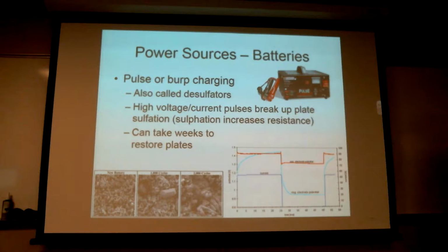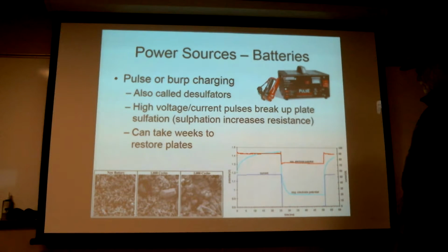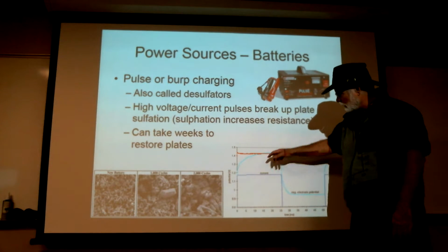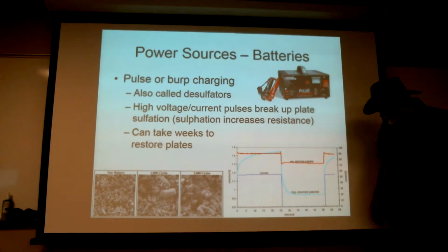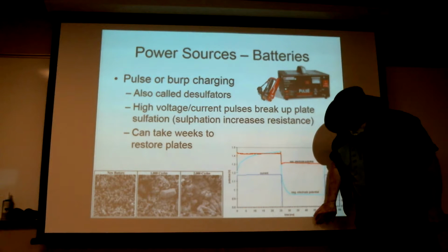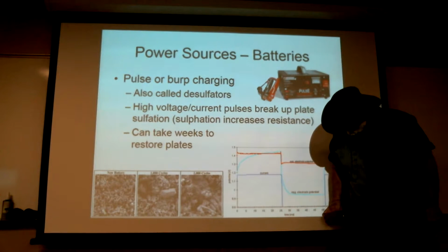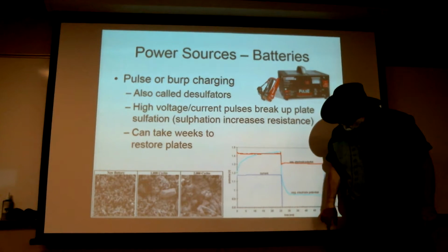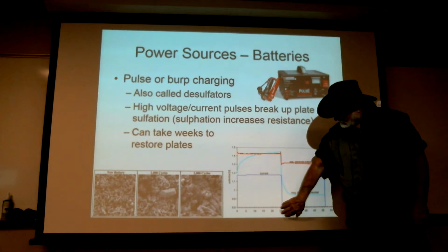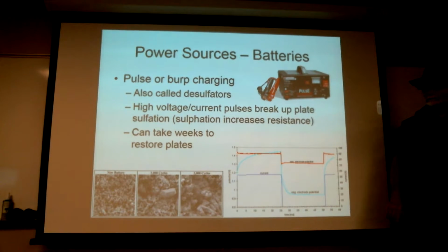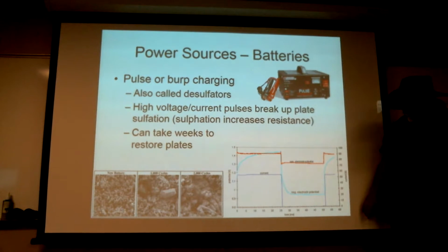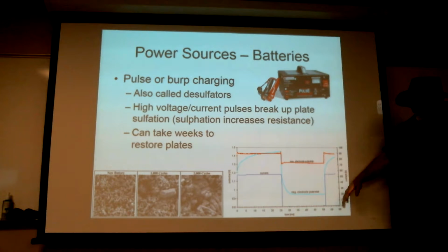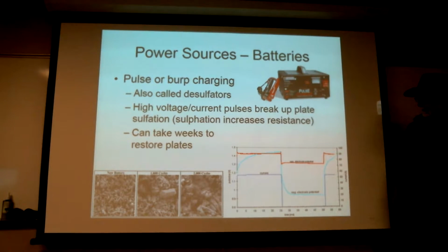And if you look at it on an oscilloscope, you'll see voltage potential or current potential going on, big jump, off. And in here, this is going to be in milliseconds. So in this one, we're actually going to go 25 thousandths of a second at approximately 55 amps. And then again, 25 or 26 off, and then on, and then off, and then on, and then off.